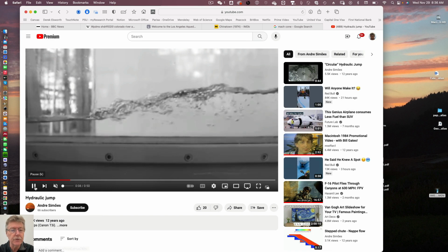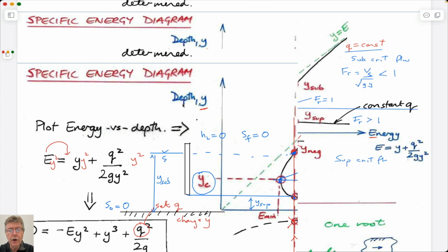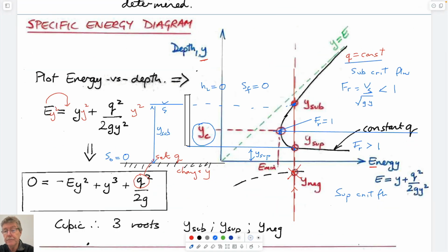And the easiest way of doing that, of course, is if we come back to looking at this: if the flow is constant along this curve, then to get from this upstream behavior that is supercritical, so this is a shallow flow, I suppose if we drew that flow on here, it would be the opposite of this. If I extend the base of the flow here, then the upstream flow looks like this, and then it goes all the way up here.